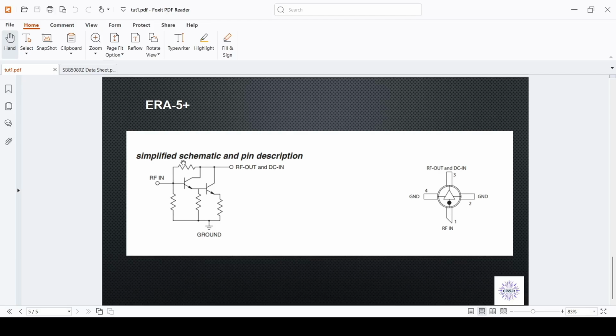You can design this resistor to be large to reduce the noise of this amplifier while also maintaining the input matching. In a future video, we will discuss different types of wideband amplifiers that we can make for integrated circuits, which makes this more clear. But for now, I just wanted to show how this transistor is probably made.